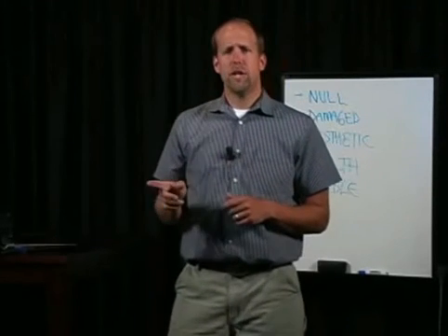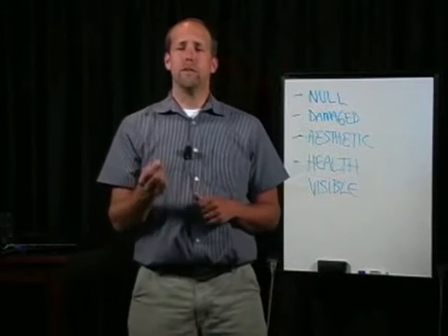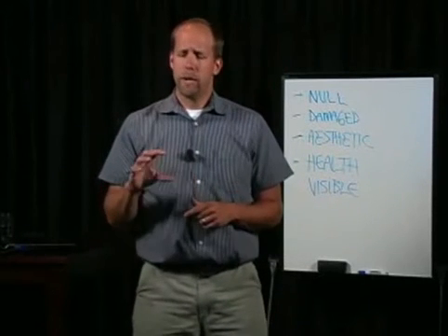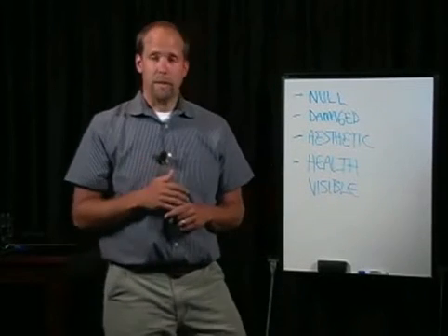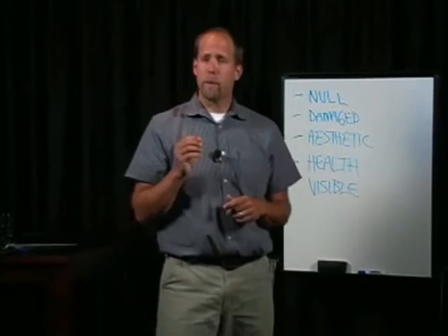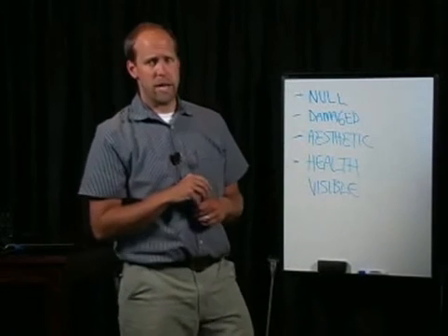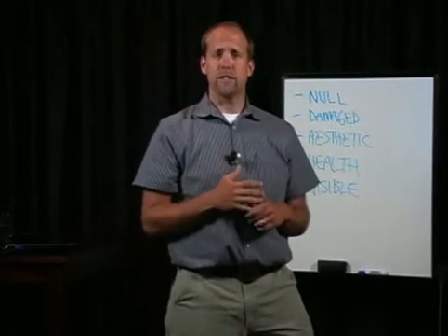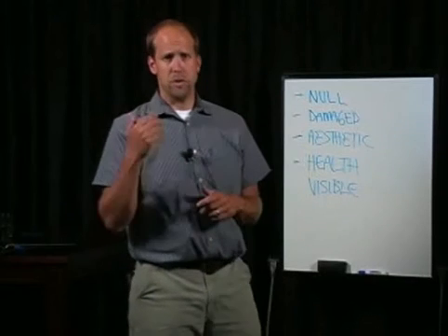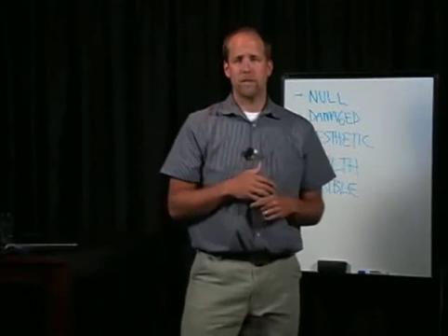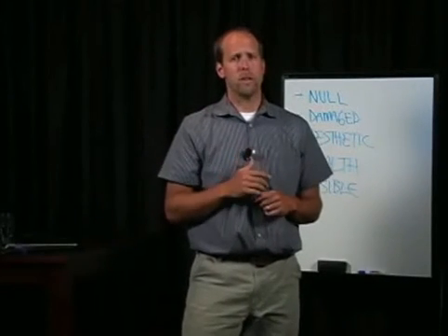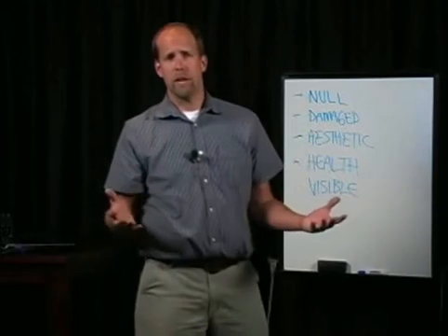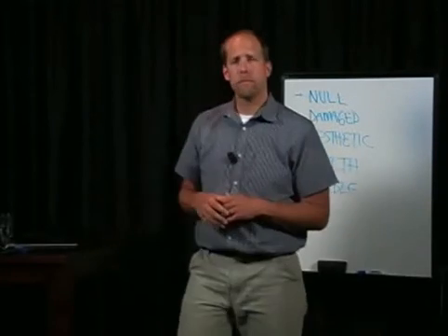An inspector should make good use of them as relevant, suitable, or pertinent in interpreting laboratory results and making recommendations to their clients. The purpose of a non-invasive visual examination is to report areas of concern: moisture intrusion, water damage, musty odors, apparent mold growth, and conditions conducive to mold growth.